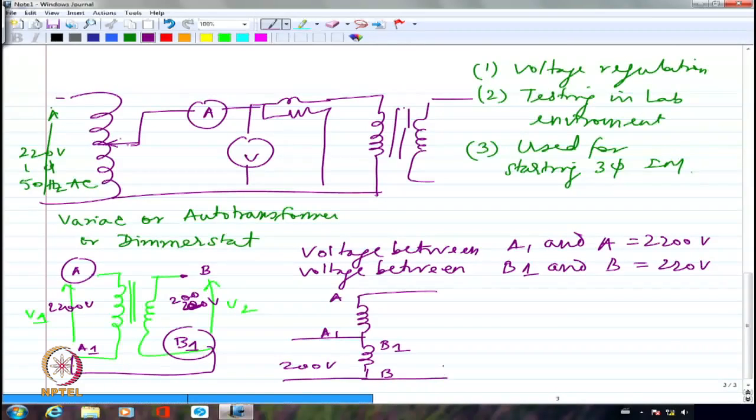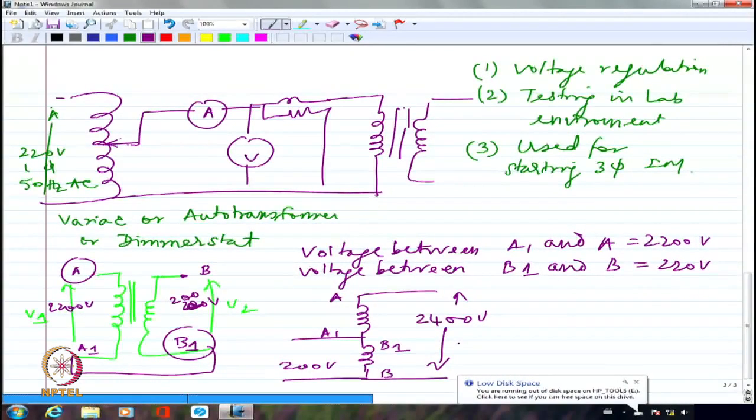This is series addition. This is added because B1 and A1 directly have the same kind of polarity, and when I connect them together, I get the total series addition. So when I actually measure, I am getting 2400 volts. If I had wanted 2000 volts, if I had...